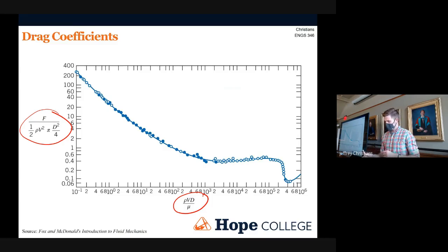If you look at this data here, you can see it's kind of a weird function. Like it's kind of swoopy and then it does goofy things. So again, we don't know beforehand what the function is. This doesn't tell us anything about that. It tells us that if we did 2 wildly different experiments, if the Reynolds numbers match, the drag coefficient is going to match. So it doesn't matter what experiment we're doing. If we have a Reynolds number right there, our drag coefficient is going to be the same. If we did an experiment under one set of conditions where the Reynolds number is 5,000, that's going to give us an insight into a different experiment at a different set of conditions where the Reynolds number is also 5,000. So we can match across experiments.